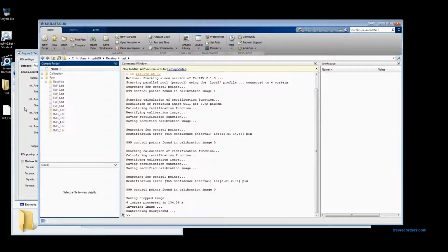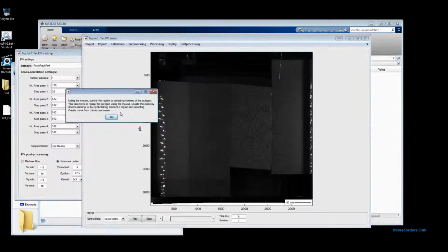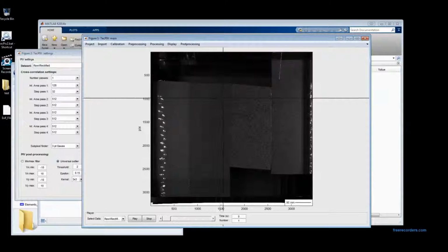So this is what we obtain. We can then play with what we display. We have the displacement shown as the vectors here. We have a vector derivative behind and the deformed model. So display settings. We can change how many vectors we have. We can have every 2, apply, more, maybe too many now. So 4 was a good setting.